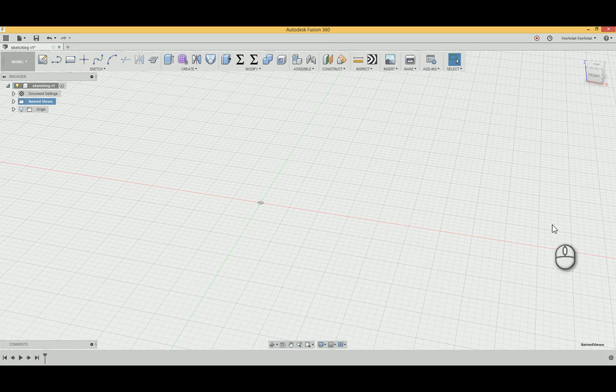Okay, here's the thing that gets people who are beginners. Most of the time, 98% of the time, for all functions when you're drawing or doing anything, you will click at a spot. You click, let go, move, and then click again. Whereas in a lot of programs, people click and hold and drag. We don't do that very often in CAD, okay? And that's because when you click, it allows you now to put numbers in or change things in the design. So get used to this whole notion of just clicking, letting go, moving, and clicking again, okay?